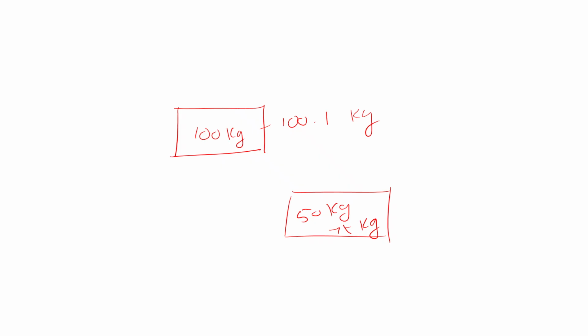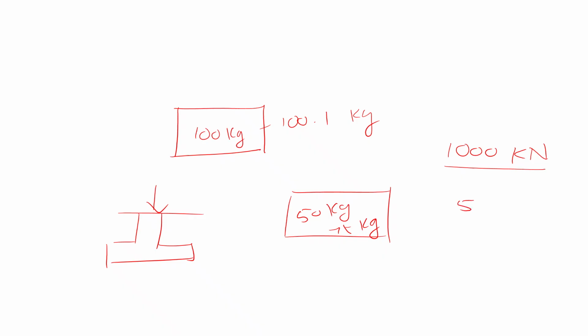Likewise, to ensure my foundation is safe, I'm not going to load it to the maximum. Rather, I will restrict the load that is being applied on it and ensure that it is safe both in terms of gross and net scenarios. So for example, after doing all the calculations, I found out that the load that the foundation can withstand is 1000 kilonewton. Do you think I will apply all the 1000 kilonewton on it? No, I will restrict myself to say, for example, 500 kilonewton or 750 kilonewton, like this.